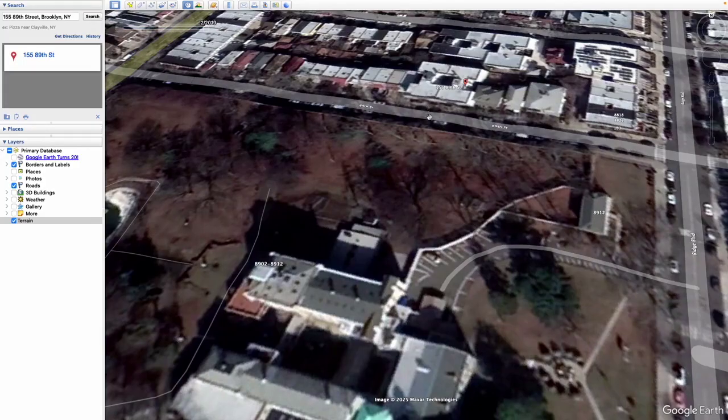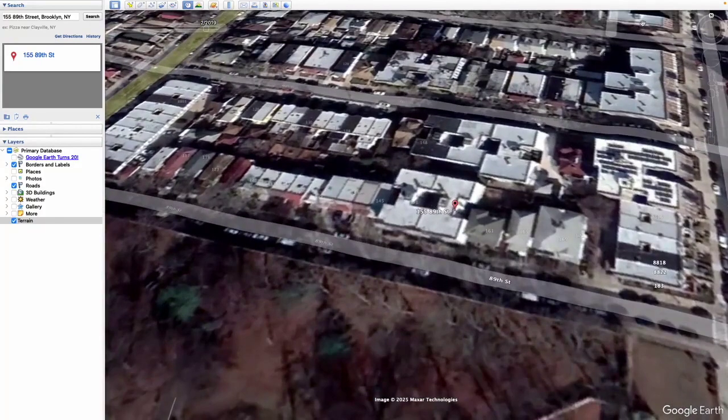It's important to remember that imagery may not always be available for all buildings, particularly in remote or rural areas, or for buildings that are very new and have not yet been imaged. If you intend to use Google Earth as part of an inspection, the best practice is to quickly look up the building and determine what imagery is available before conducting the site visit.